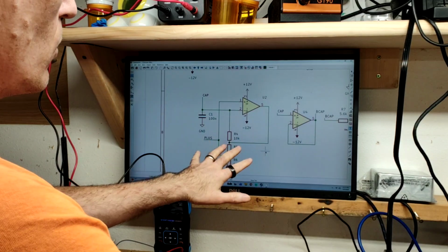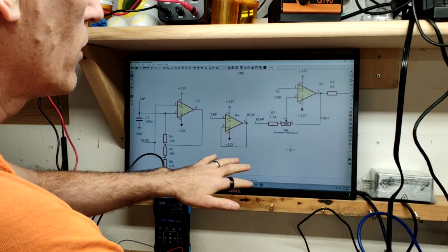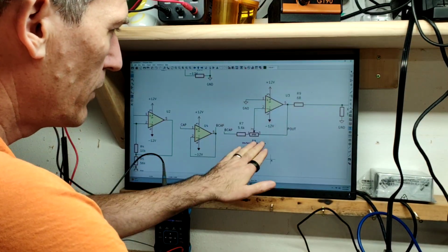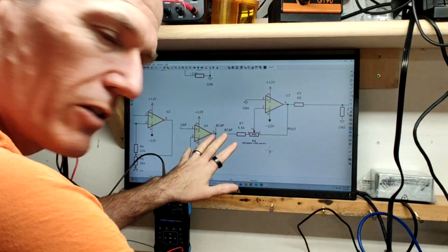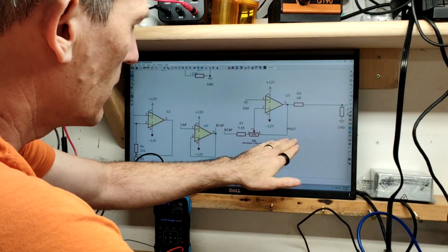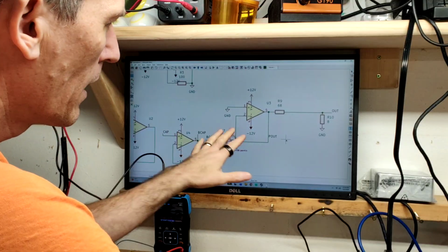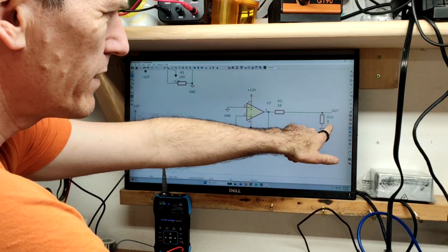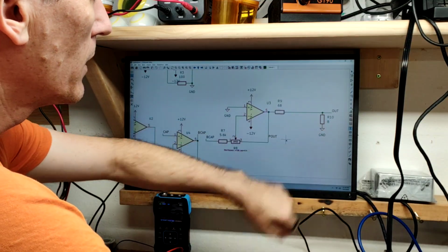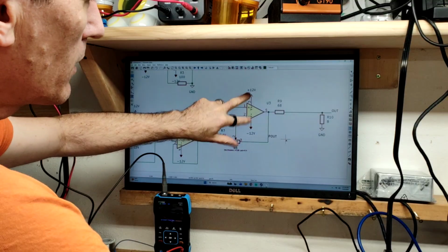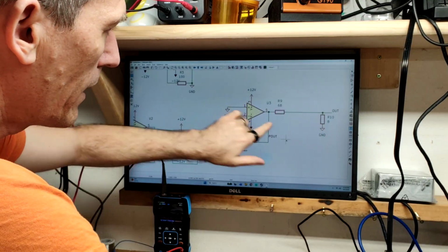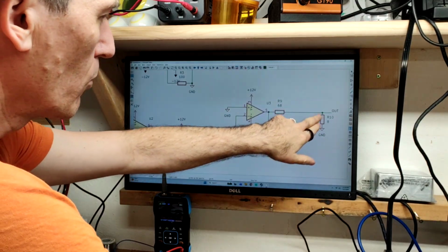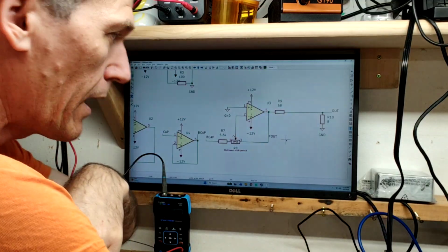Okay, so then let's skip over this for now. This is an amplifier. I don't think I'll talk about how exactly this amplifier works, but we'll come back to it in a second. It allows us to amplify that signal, and so I can adjust it with this variable resistor. And then this 8 ohms out here, this is my speaker. And this can go from -12 to 12, right? And so I've set this up here, 68 and 8, so that the voltage divider won't send more current or more voltage across my speaker than it can handle.